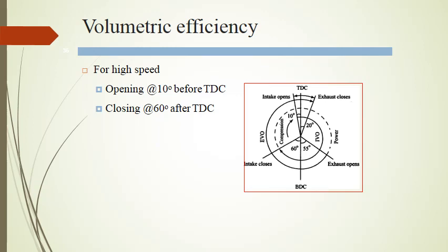The chosen intake valve setting for an engine operating over a range of speeds must necessarily be a compromise between the best setting for the low speed end of the range and the best setting for the high speed end. The timing of the exhaust valve also affects the volumetric efficiency. The exhaust valve usually opens before the piston reaches bottom dead center on the expansion stroke. This reduces the work done by the expanding gases during the power stroke, but decreases the work necessary to expel the burned products during the exhaust stroke and results in an overall gain in output.